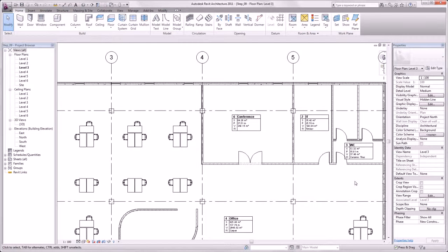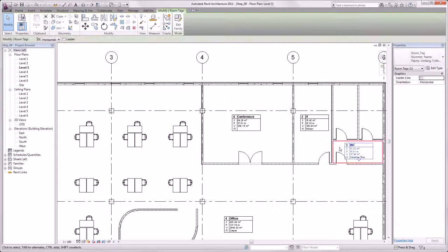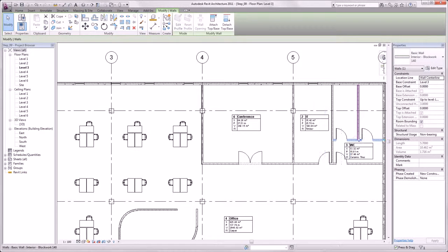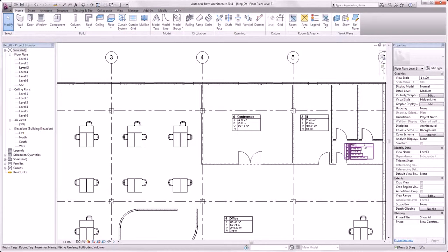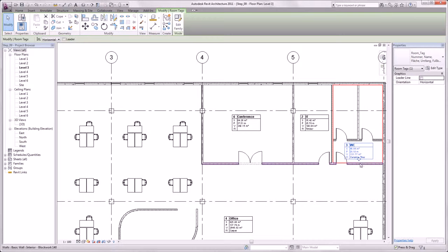On the right side, if you click the boundaries of our toilet, you see only the entrance area is calculated. Our calculation also should include the other 2 rooms. So we select these 2 walls. And in the properties, we demark room bounding. And if we now click our boundaries again, you see the whole room is now calculated.